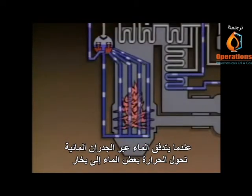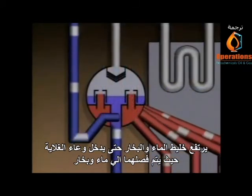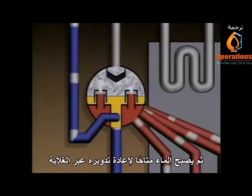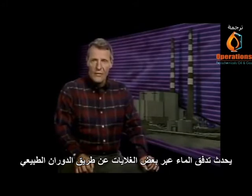The water walls are exposed to the heat produced by burning fuel. As water flows up through the water walls, heat turns some of the water into steam. The mixture of water and steam rises until it enters the boiler drum, where it's separated into water and steam. The steam rises to the top of the drum, and the water remains in the bottom. The water is then available to recirculate through the boiler.